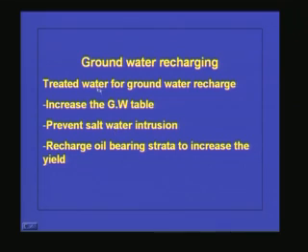And we can also use the effluent for groundwater recharging. The treated water for groundwater recharge increases the groundwater table, prevents saltwater intrusion, and recharges oil bearing strata to increase the oil yield. But whenever we go for groundwater recharge, we have to make sure that all the pollutants, whatever is important in terms of health, are removed from the system, otherwise the entire groundwater will get polluted because of the pollutants present in the system.